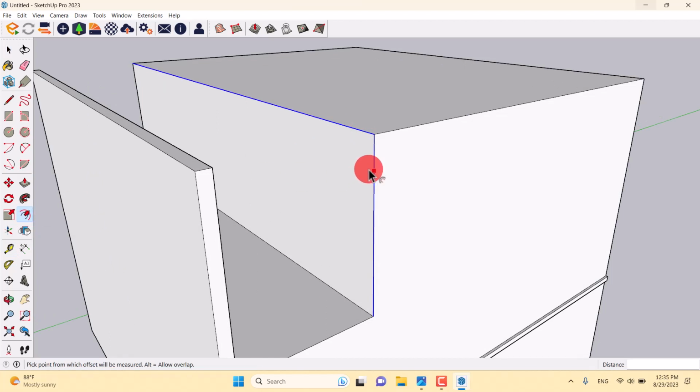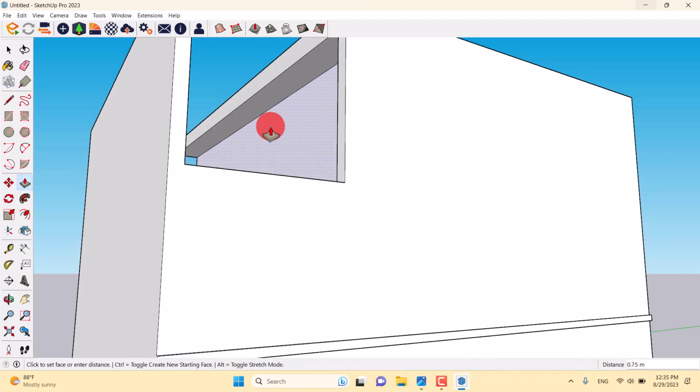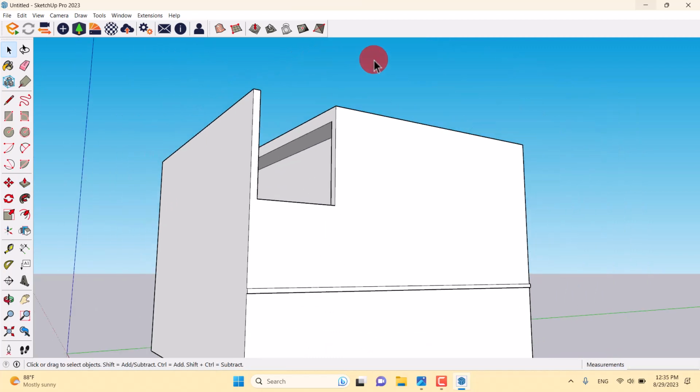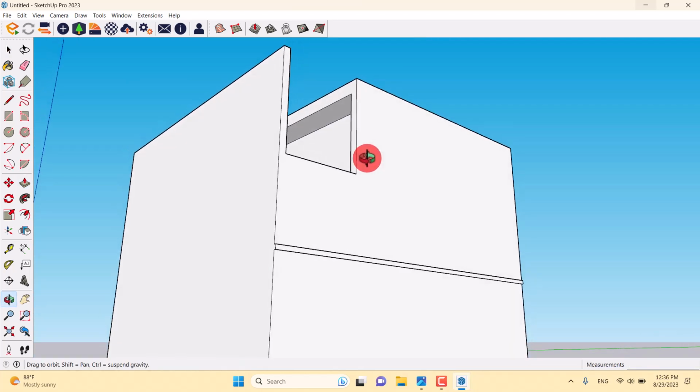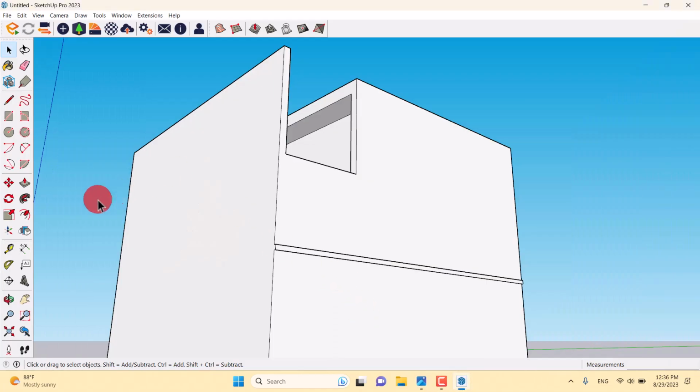I'm going to click on the offset option and take some offset about maybe 26 centimeters. I can take it a little bit to the downside, about 0.2, and now I can extrude it to this place about maybe 1 meter, and this is my final result. But I can make these walls a little bit thicker than usual.